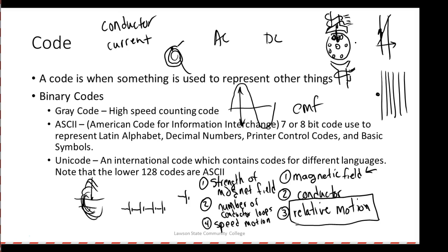So we have no electrical connection between the rotor and the stator because the current in the rotor is induced in there. So that means we call these squirrel cage rotors. The conductors are actually shorted out on the end. They're at a slight angle. So this actually here would be the conductors.